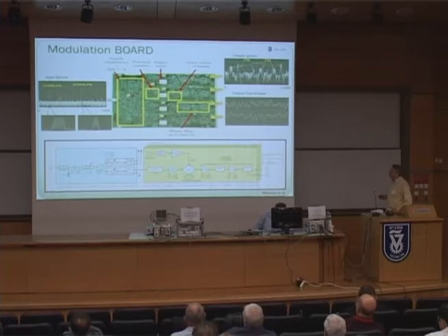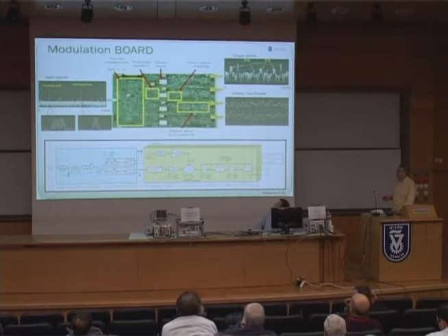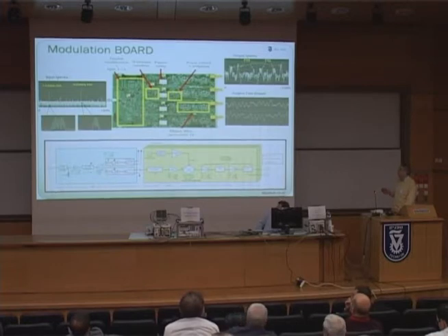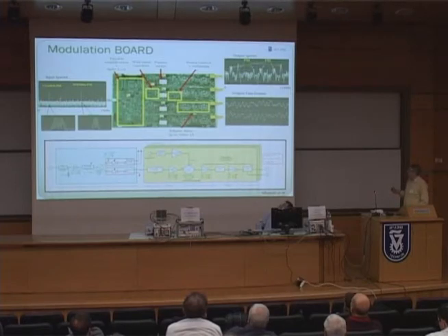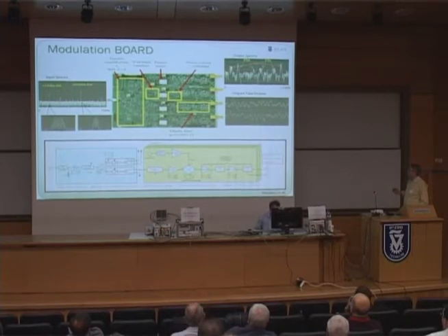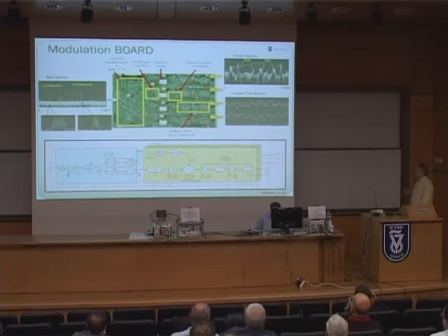You can't really see this in this small picture, but down here is a blown-up version. This is FM, and this is a PM modulated signal. Over here on this side, you have now the aliased signal, the 3 slices. So we have 3 times the FM signal and 3 times the PM signal folded together into the 3 slices. From every output, you wouldn't see much difference in the spectrum, but you see the difference in the time domain.